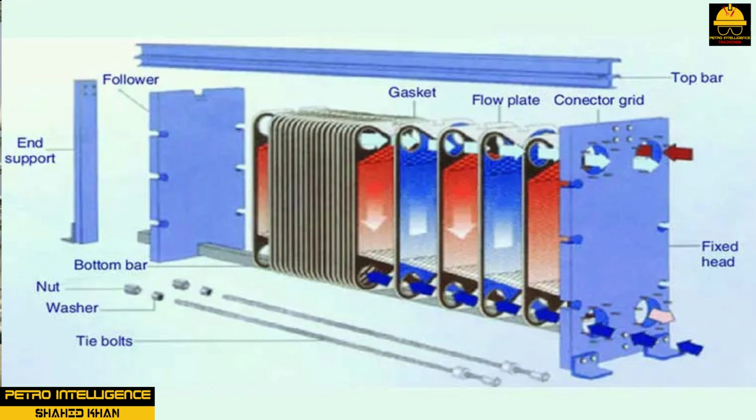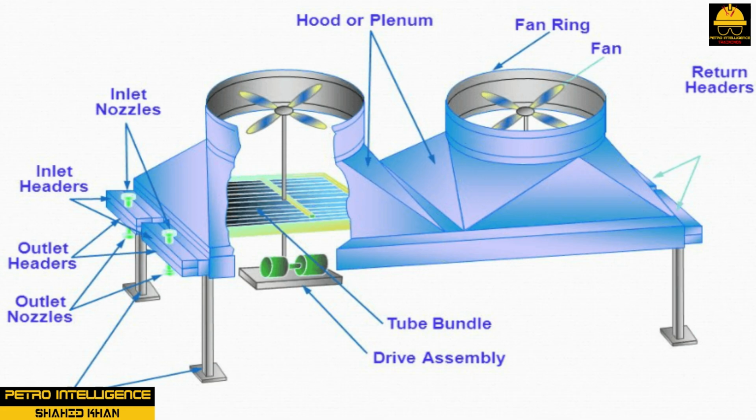Operating limits of 350 degrees Fahrenheit to 500 degrees Fahrenheit, or 176.66 degrees Celsius to 260 degrees Celsius, are designed to protect the internal gasket. Because of the design specification, plate and frame heat exchangers are not suited for boiling and condensing. Most industrial processes use this design in liquid-liquid service.